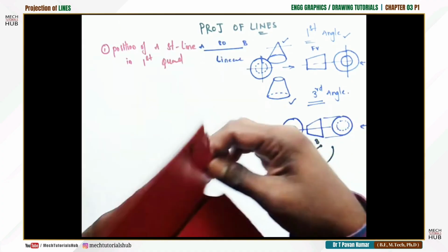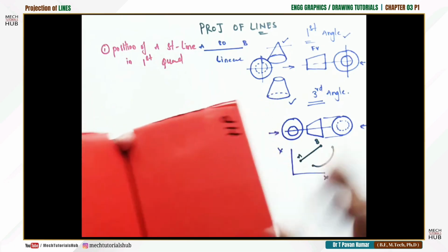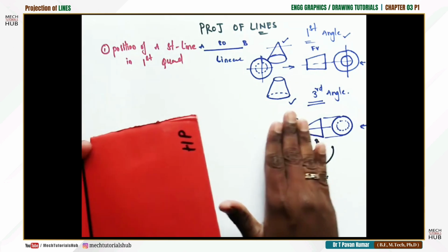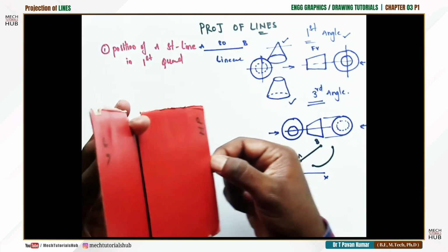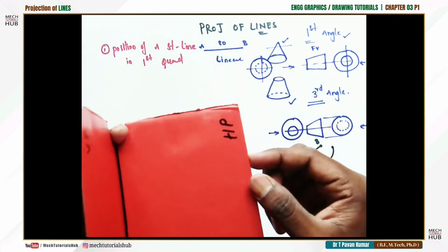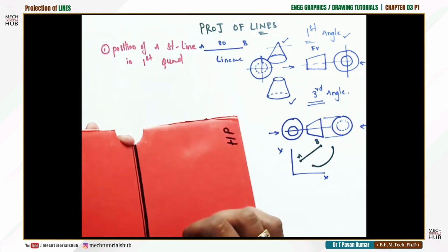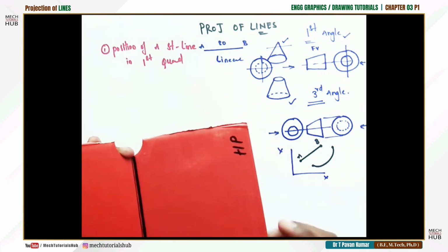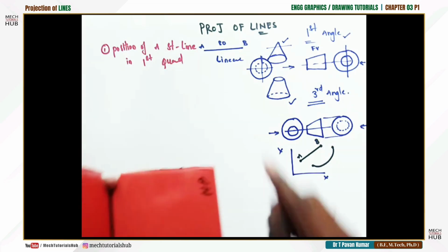Simple thing. When both the planes are 90 degrees to each other, perpendicular to each other, this can't be drawn on a plain drawing sheet, which is impossible because the drawing sheet is completely laid on the table. That is the reason we are always rotating the horizontal plane 90 degrees clockwise. Whether it is a point, line, or plane, it is going to rotate below the XY line. Let us consider this dark black line as XY, X and Y ends. This is the horizontal plane, vertical plane.